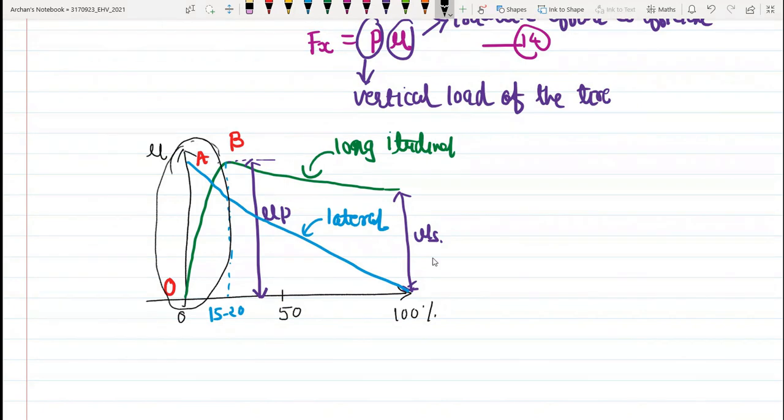This small slip is caused by the elasticity of the tire rather than the relative slipping between the tire and the ground at the contact patch. When a tractive torque is applied to the tire, a tractive force is developed at the tire-ground contact patch. At the same time, the tire tread in front of the contact patch is subjected to compression, so a corresponding shear deformation of the sidewall of the tire is also developed.